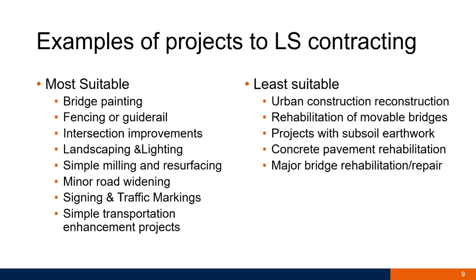You would say repair this wall, but we don't know how to measure the repair in this wall unless you start doing that work. And also projects with subsoil earthwork, definitely when you have something beneath the soil, you don't know exactly what you are going to encounter in the project. So this is a level of uncertainty that is not desirable with using lump sum.